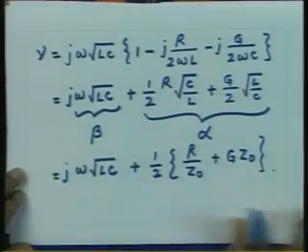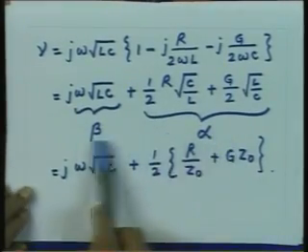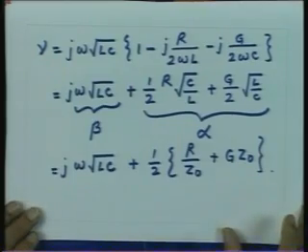One would then like to convert this condition, R less than omega L and G less than omega C, in terms of these secondary parameters or in terms of the relationship between beta and alpha. Since these parameters are available readily on the data sheet, if I can establish a condition between these parameters for the low loss nature of the line, then I can find out whether a particular line is low loss at a particular frequency. So, now, starting from this relationship between beta and alpha, we can find out under what condition we can treat the line as a low loss transmission line.